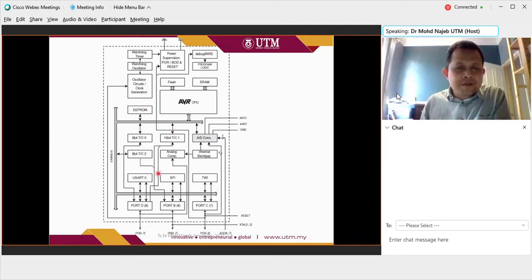So they have the UART converter, which converts to your USB. Actually it's not a USB, basically it is a UART. This UART is where you send your data from the RAM or from the flash. You send it to the UART, and the UART will send your data out into the physical wiring, into what we call the UART to USB converter, and then through the USB cable connect to your PC.